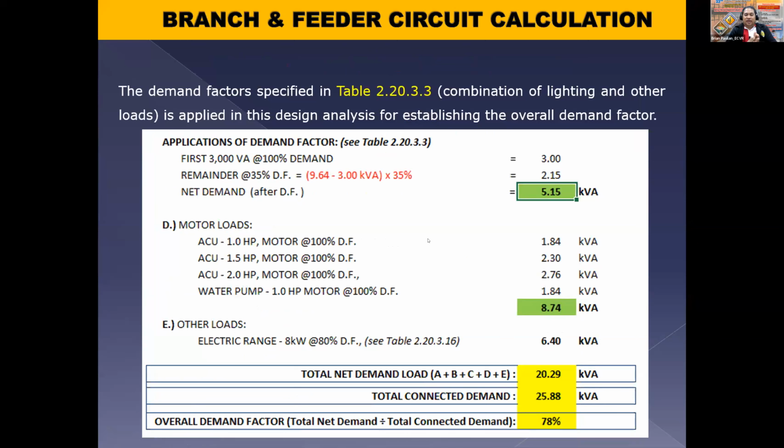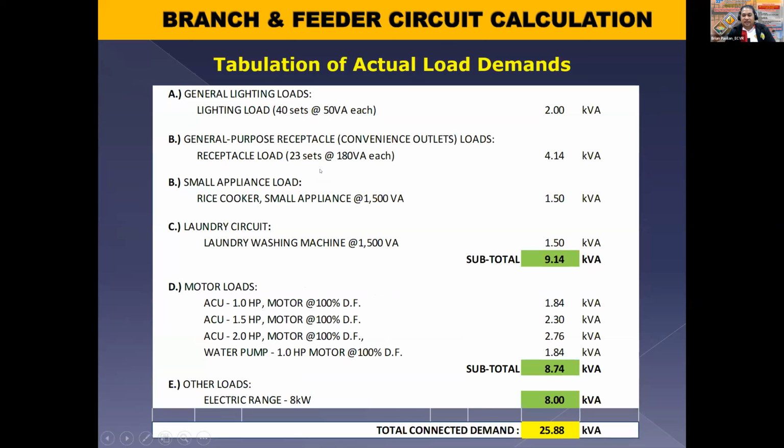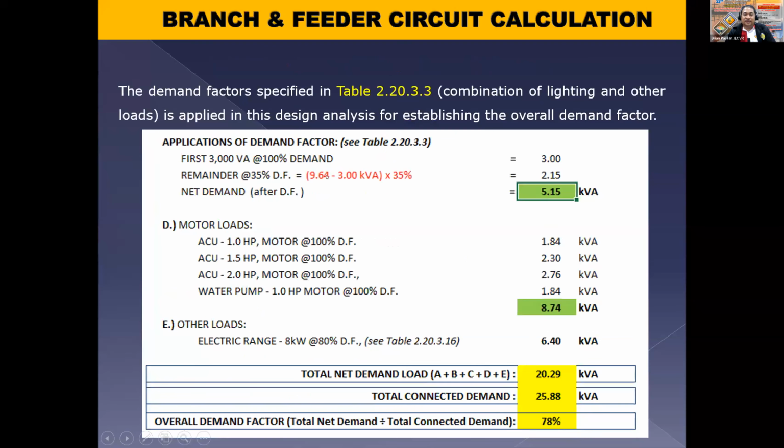Now we're going to add the lighting loads, the lighting outlets, with the lighting demand. So this is what we got, 9.64, we included the outlets demand.